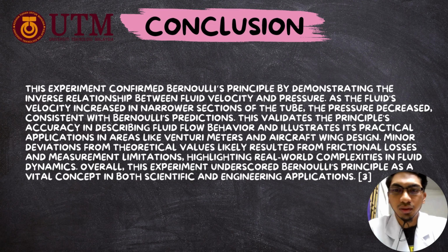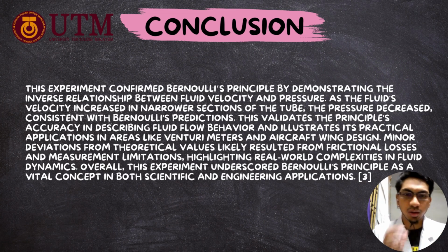For this experiment, we confirm the Bernoulli principle by demonstrating the inverse relationship between fluid velocity and pressure. As the fluid velocity increases in the narrow section of the tube, the pressure decreases, consistent with Bernoulli's prediction. This validates the principle's accuracy in describing fluid flow behavior and illustrates its practical application in areas like the venturi meter and aircraft wing design.